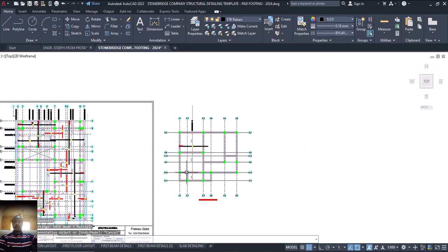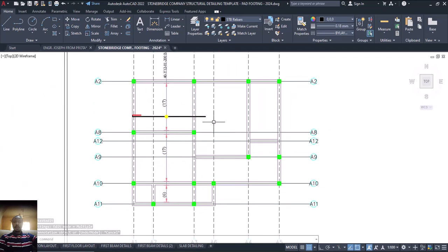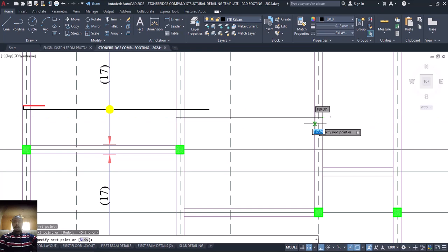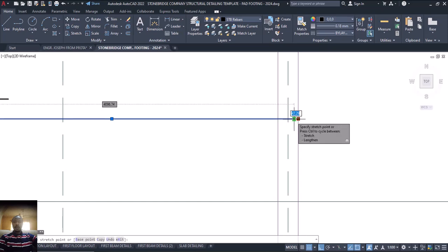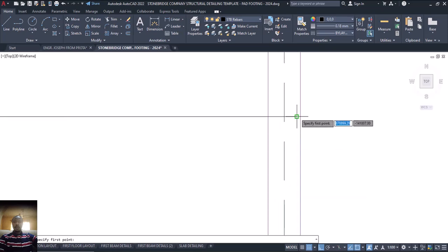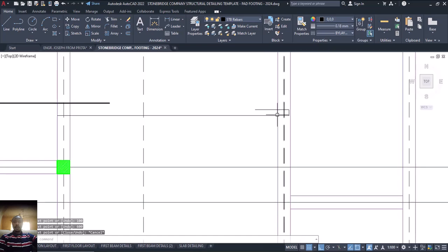That's clear. Perfect. So now once you have done this one like this, the next thing is this place. Is that okay? I'll pick my reinforcement L, enter. Now from this place here under it, I'll come to this place here where there's a staircase. Is that okay? I'll also have my cover, which is 25 away. Then put my reinforcement up, which is 100, and I've explained how we got that 100. Come back as 600. Is that okay? That is that. My return bar is 600.